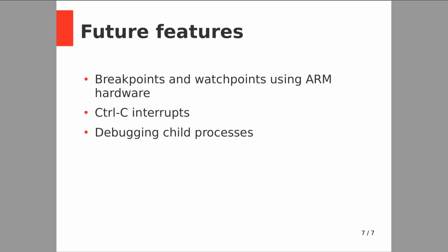You can set what memory address you want for a particular instruction, and it will automatically trigger an interrupt once you hit that point. So you just set that into a breakpoint register. The same thing happens with watch points. If you set the address of a variable in memory, then when that changes, it will automatically trigger an exception, and you can see what the variable changed and everything.